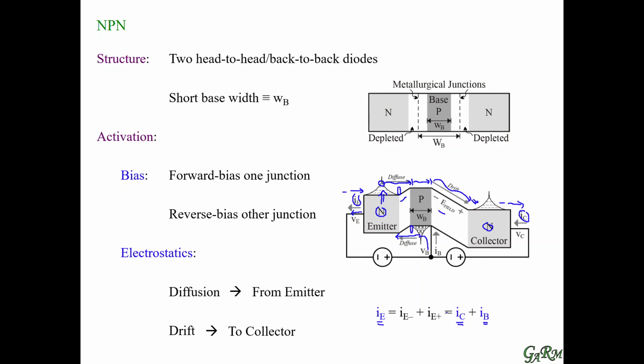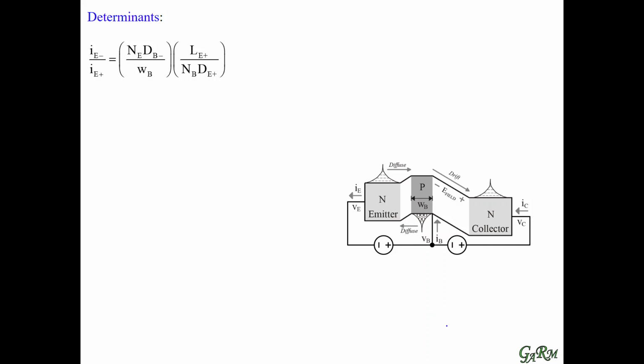So this base current is being fed into the device along with the collector current, and the emitter current is the one that basically drains those two currents. The emitter current is also composed of two components: the electron current, that is the one that actually reaches the collector, and then the hole current that is coming from the base. So let us quantify these currents.